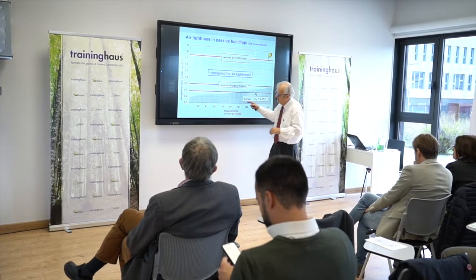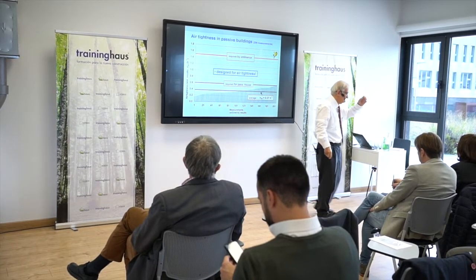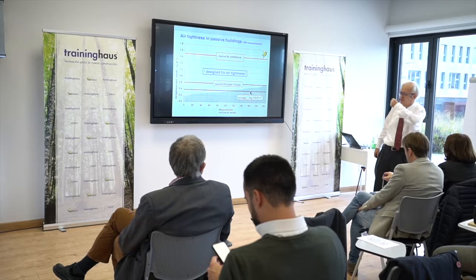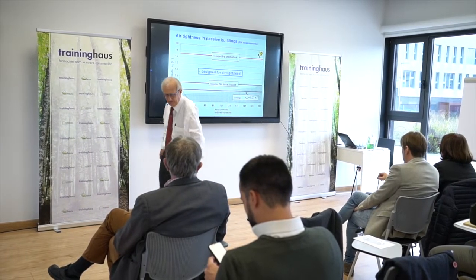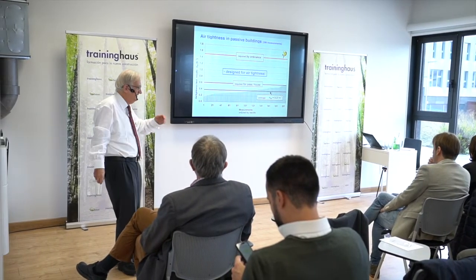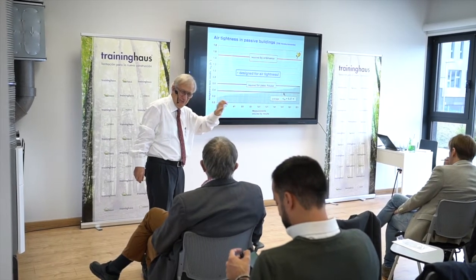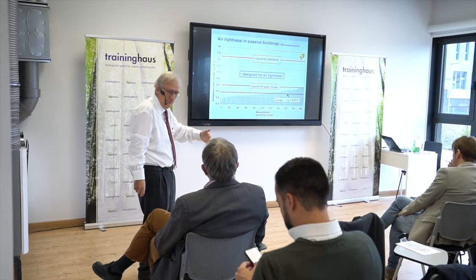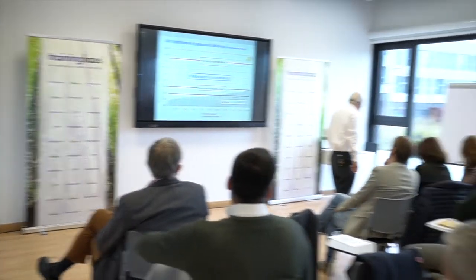Now, I won't talk about that, but I will just tell you, there's no reason to go even lower than say 0.1, or so; there's some kind of extra sports where we can do the most airtight building. I just have seen in Britain they managed to have 0.02 or something like that. I have to be honest, I think that's nonsense, because you don't need it to be that tight, and if I just open the window once and close it, not completely in a proper way, you will add to that 0.1, 0.01, another 0.05 or something like that. So it doesn't make any sense to go much beyond that. Okay, there's also another reason I don't talk about that.